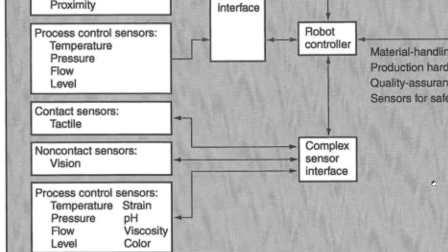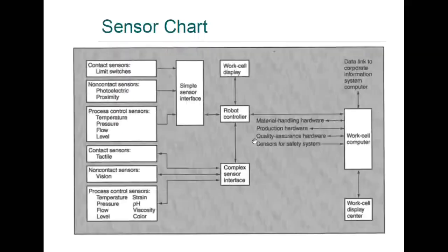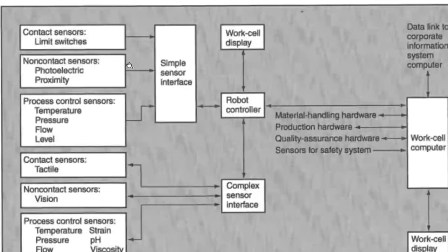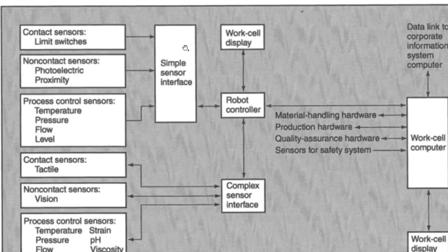Okay, so anyhow, these are just some of the various types of digital sensors, and then they would go into a digital input card that would usually be part of the controller, or it could be a separate input device. Then it maybe goes to the robot through an Ethernet connection or Profinet or DeviceNet sort of network connection, and is sent to the robot controller.